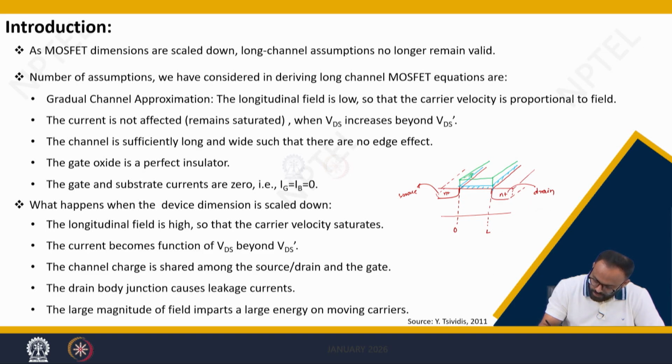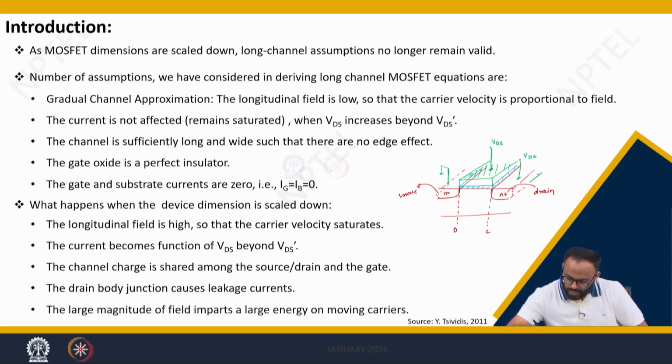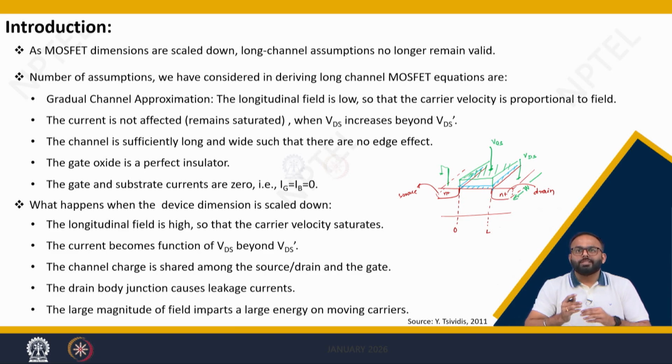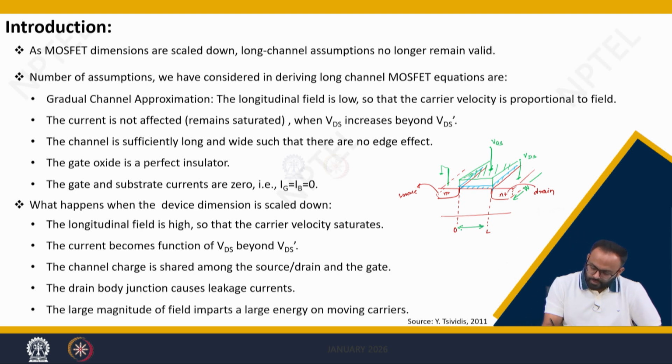In this gate you are actually applying the gate voltage Vg, and here you are applying the drain voltage Vds. This is the source, you are keeping it grounded. This side or this dimension is defined as the width of the device, because a MOSFET, in a physical sense, is a 3D structure. So, we do have length, we have width, and the oxide thickness, or this is the thickness direction, correct.